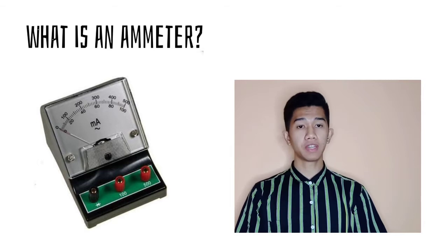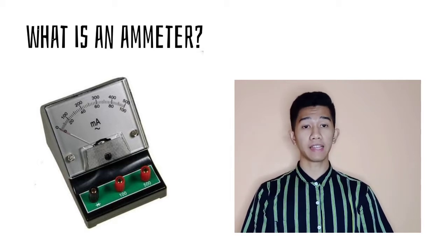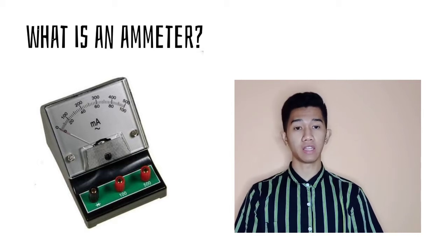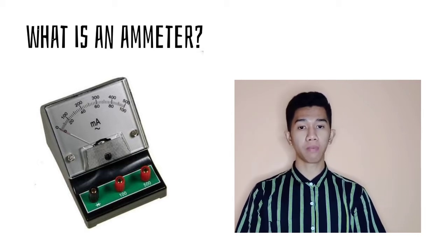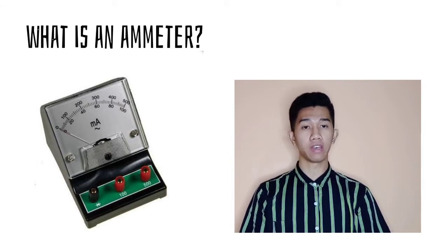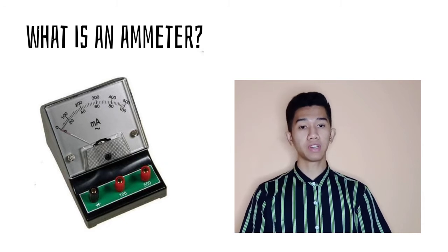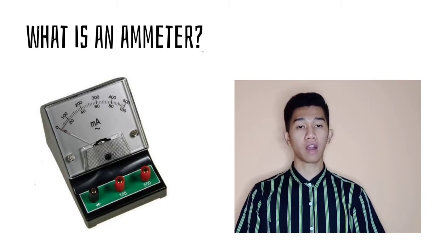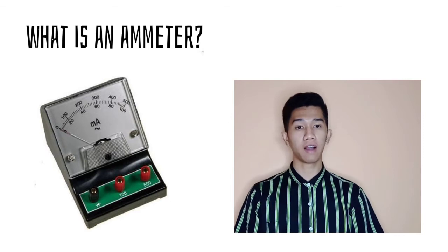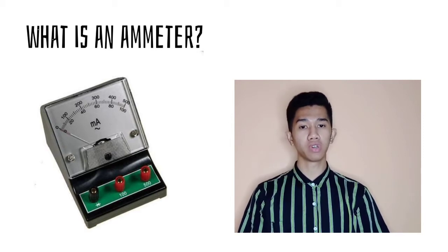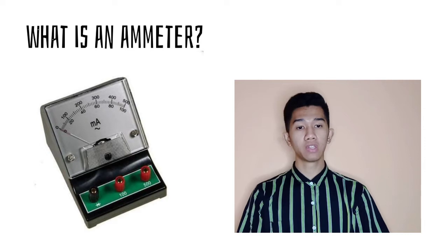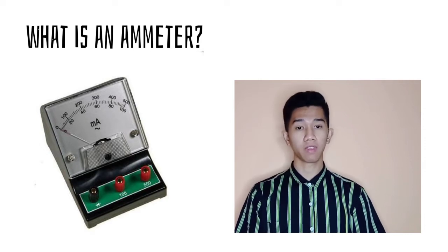Ammeter. The ammeter was invented by an Austrian electrical engineer named Friedrich Drexler in 1884. An ammeter is an instrument for measuring either direct or alternating electric current in amperes. An ammeter can measure a wide range of current values because for high values only a small portion of the current is directed through the meter mechanism. A shunt in parallel with the meter carries the major portion.